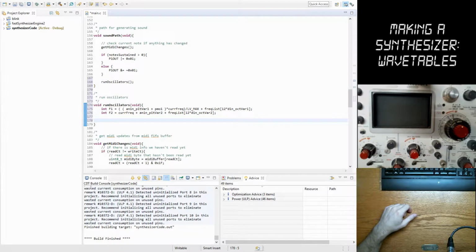All right, now the next thing is, in order to jump through the waveform list, what we do is we jump our index with respect to time. If it's a higher frequency, we jump through the table by moving our index faster, so larger jumps between time steps. And as that grows, it'll grow out of bounds outside of the wavetable size. So every time it jumps outside of the wavetable size, we'll have to scale it back in and start it over in the wavetable at the correct point. So once you run out of the wave, you repeat the wave, and you have to do that rollback maneuver.